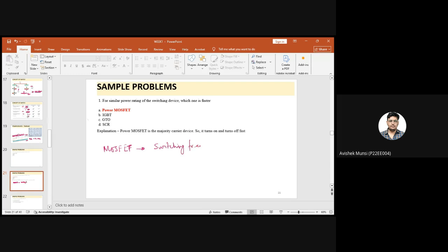I also mentioned that GaN based or SiC based devices can be used at megahertz level. In silicon devices, we can use 100 kilohertz, 50 kilohertz, 200 kilohertz, up to which is proper. But many of you have answered IGBT, and the switching frequency of IGBT is limited to hardly 20 kilohertz, 15 kilohertz. There are some modules which you can use up to 40 kilohertz. So that was a wrong answer.